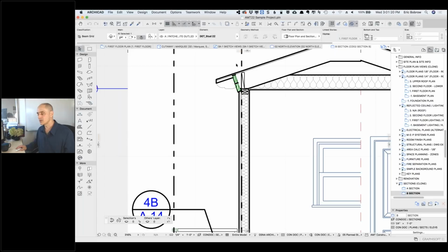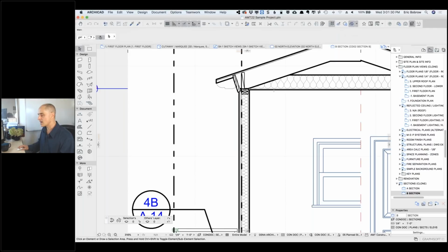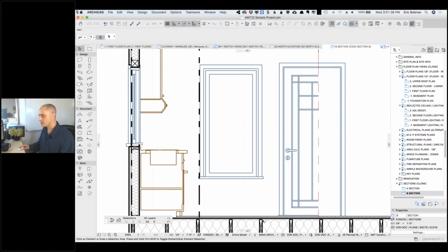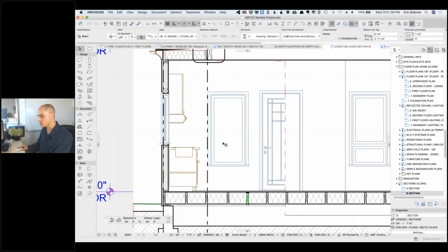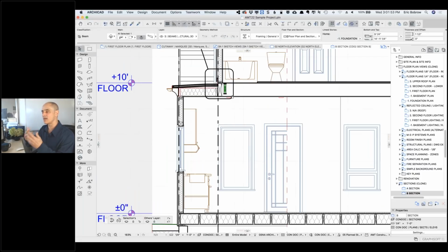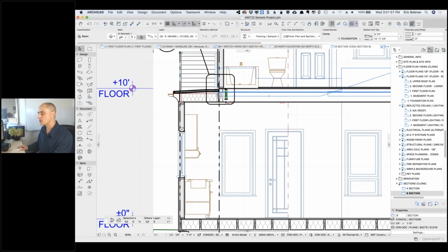Now it turns out that you can get exactly the same effects by just varying the profile. So here's what I've got in here. I'm just going to do something real quick and dirty here. I'm going to take this element and drag a copy up to here. I just use the drag with the Option or Alt key to get a copy. So now this one still is there, but this is a 3D element. Now it's probably sticking out through the building in the wrong way, but we'll just get it here.